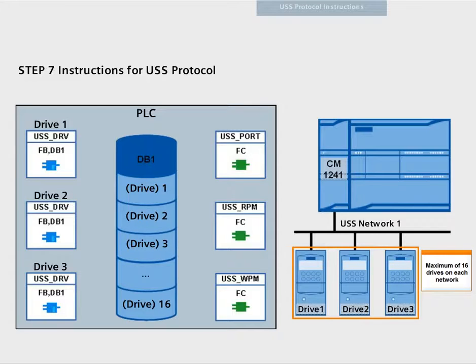If more than 8 parameters are required, the read parameter function can be used for reading, and the write parameter function can be used for writing the drive parameters. The 2 functions must also be called from the OB main program.